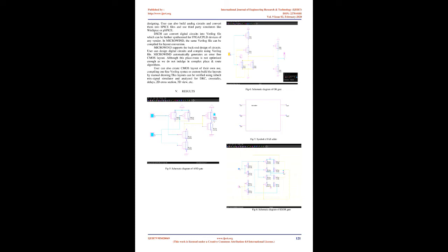In this architecture, after generating the partial products, accumulation of partial products and final addition are done in different stages. When the final stage contains only 2 rows, then final addition is done. The number of rows of partial products in a particular stage can be expressed as R(i+1) = 2·floor(Ri/3) + (Ri mod 3), where Ri gives the groups or stages, and N equals the number of bits.